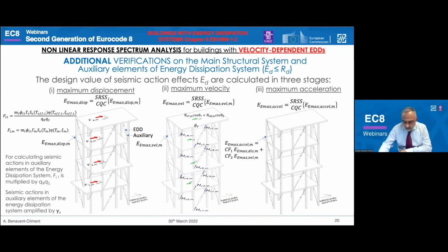Okay, besides the main energy verification explained above, it is necessary also to make additional verifications on the structural elements of the main structure and on the auxiliary elements of the energy dissipation system. More precisely, we have to verify that the design value of the seismic action effects, what is called here ED, is smaller or equal than the design resistance. ED must be calculated